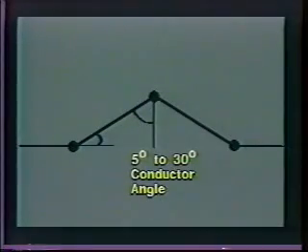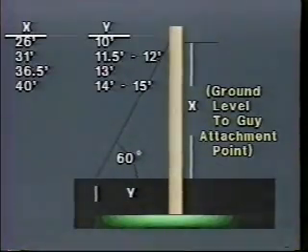As the conductor angle becomes more pronounced on an individual structure, both the conductor support system and neutral wire system change to allow for the transverse loading. When the conductor angle is more than 5 degrees, a guy assembly is usually added, splitting the angle of the conductor legs to distribute this load equally. The guy angle should be between 45 to 60 degrees, with 60 degrees being the minimum.